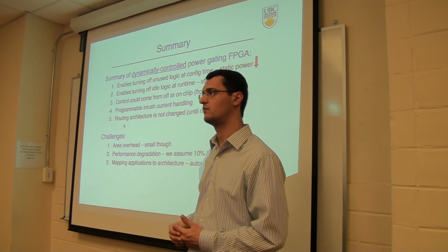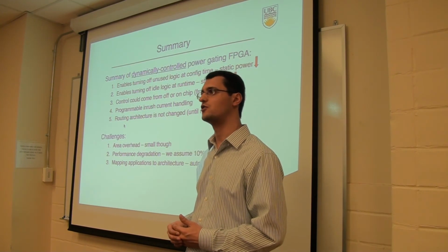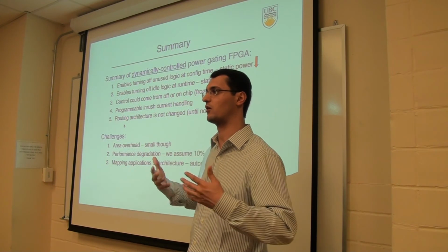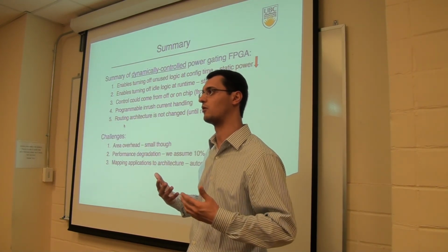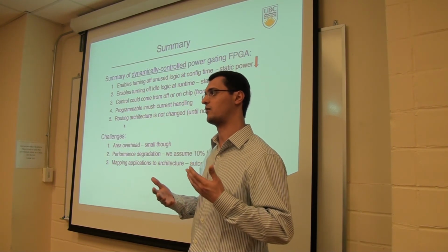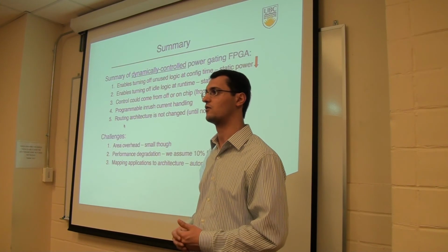I'm just wondering specifically how you model it. Do you have typical inputs? I assumed the worst case inputs, like all the inputs to the region being, for example, all on or all off, to find the worst case size for the sleep transistor.